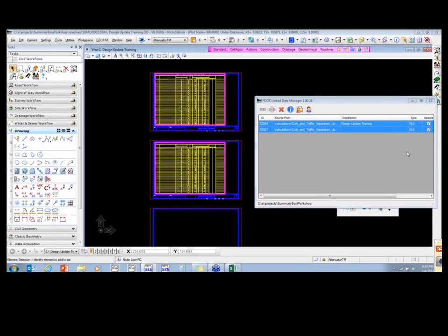You may want to break up lane lines versus what's in your median openings and turn lanes, to make it easier to say, okay, I needed this much asphalt or I had this much milling, this is a turn lane, versus them going straight down the main line.